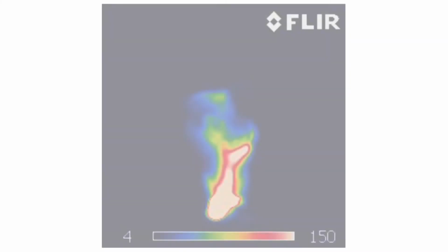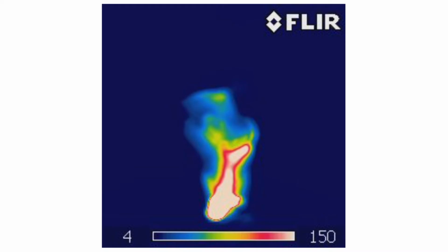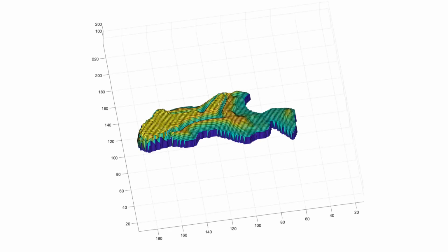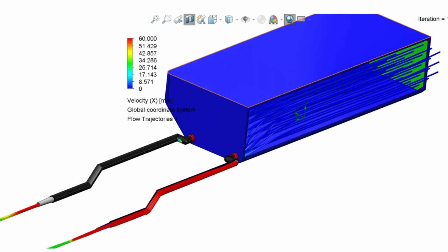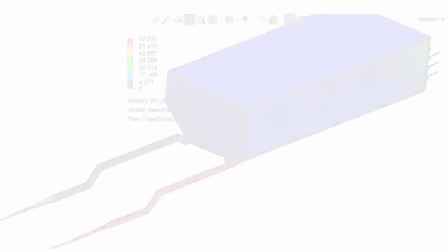The second methodology I used was with an infrared image captured with a FLIR camera, and that was used as an input to detect automatically the fire and again collect major data and ultimately activate the extinguisher after a certain threshold. Another objective was the simulation of the tank flow to know if this was acceptable. So, with a mixture of research and creativity, I used my calculations and created a CAD model, which was finally tested successfully, presenting suitable volumetric flow rates to extinguish typical fires.